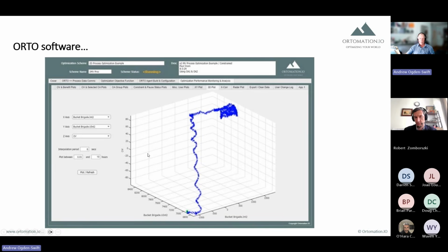And this is an example of it being applied to a wind turbine, and you can see the optimizer, there's two variables, just searching. This is power generated by the wind turbine, and you can see the optimizer searching as it adjusts the pitch and the blade tip speed, until it reaches a maximum value, and then it basically tries to find a better operating point as equipment efficiency changes.